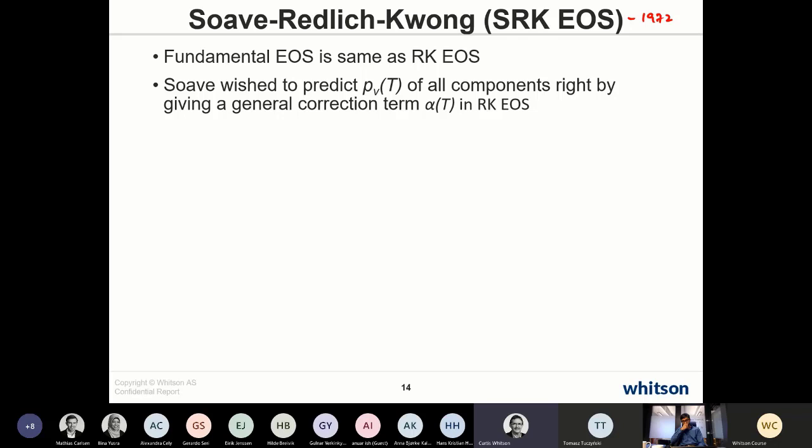A lot of people were trying to do it in the late 60s and early 70s, and what he did won favor because it was simple, very accurate, and pragmatic, and once people started using it, they just continued to use it. Once you get vapor pressures of individual components as a function of temperature, getting the K values of the same components in mixtures was trivial, using the fact that K values are inversely proportional to pressure if you know the vapor pressure.